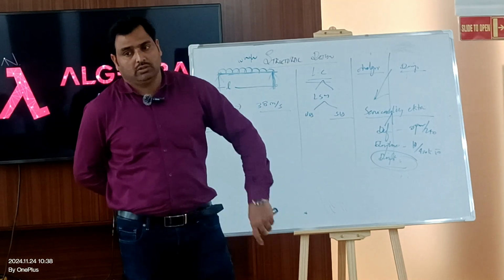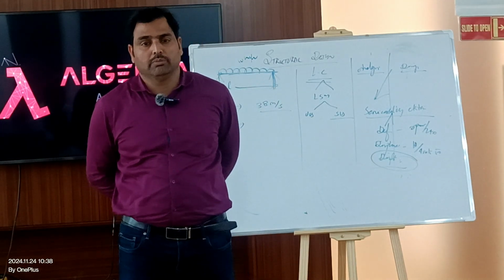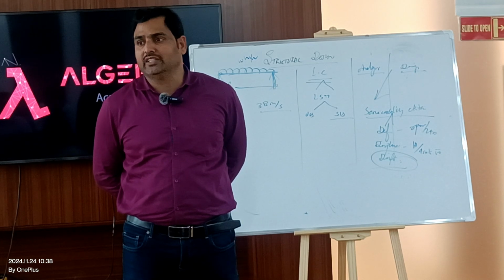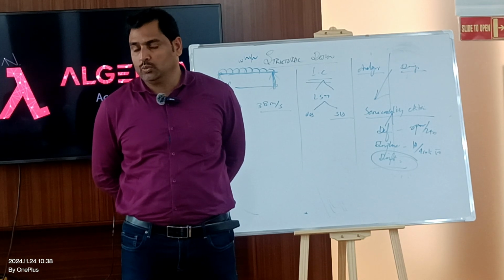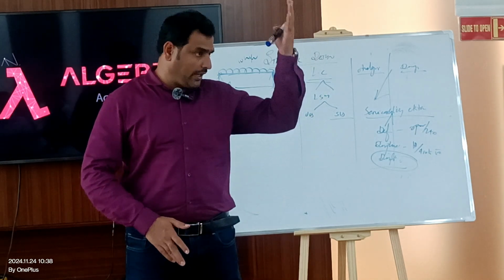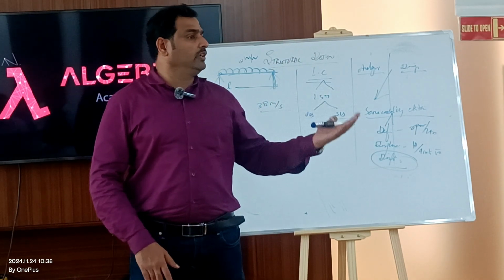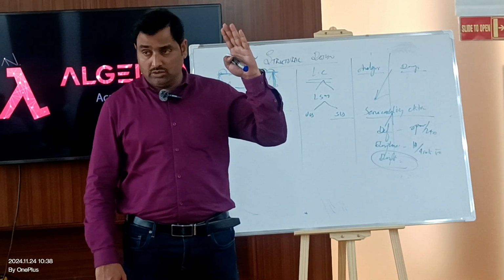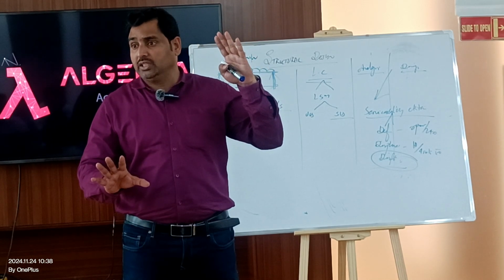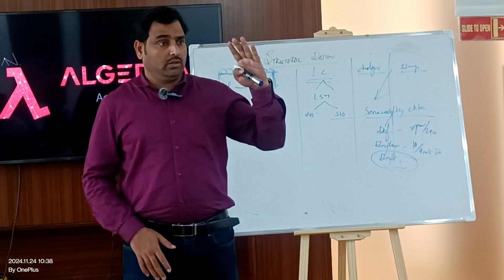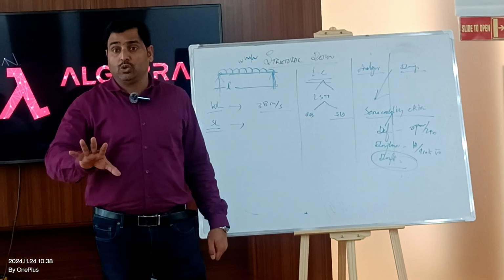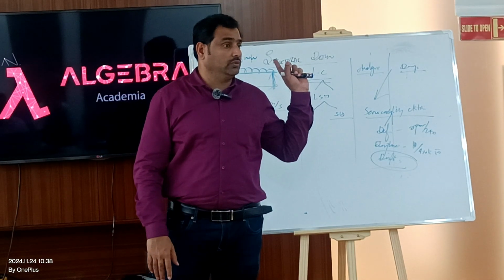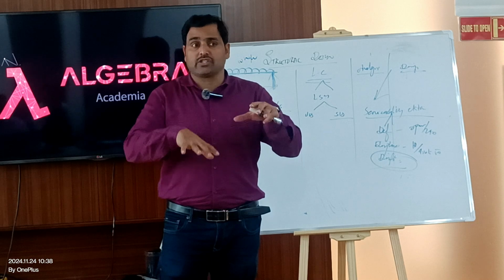Make it one thing. The building is not mandated to be governed always either by wind or by seismic. With respect to the shape of the building and the height of the building, it is going to be governed by either wind or seismic. If it is a tall structure, you may predict it's going to be governed by the wind. If it is a high-rise building, because you have several criteria, maybe your mass is different, like Dr. Haran wished the class, right? Your mass is different.